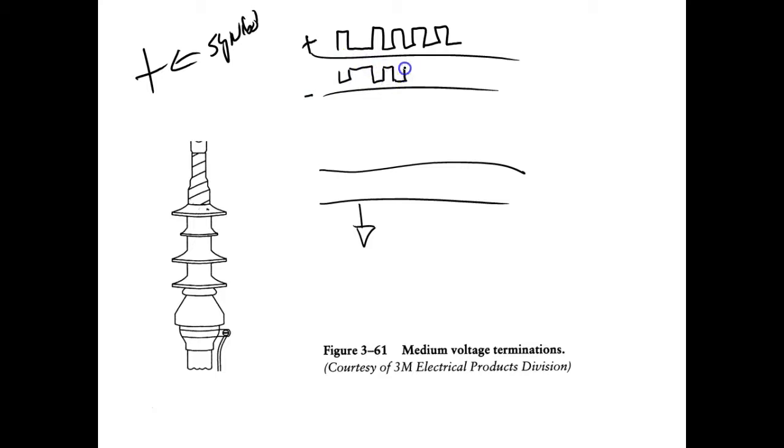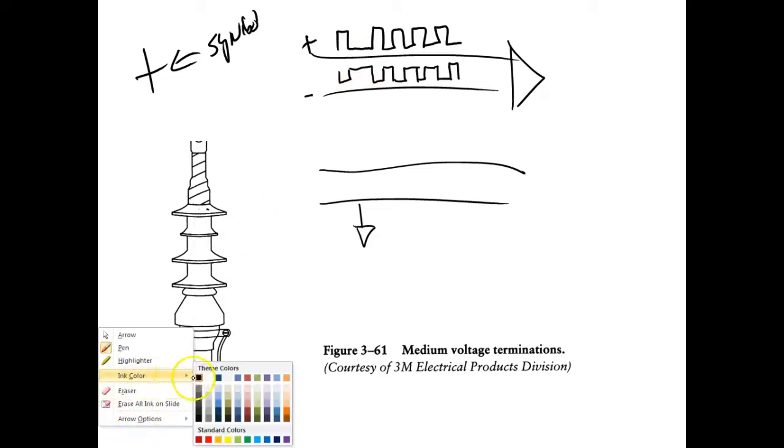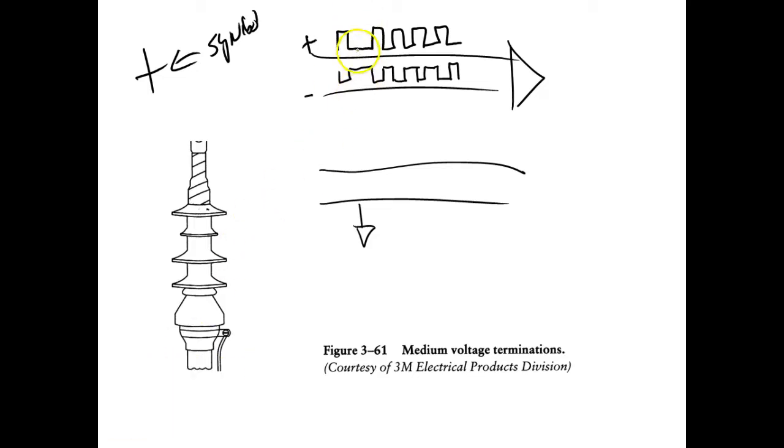If I can draw this good. So basically, it's a mirror image of that. And we came up with an amplifier called a differential amplifier, and these guys revolutionized communication. What a differential amplifier does is amplify the difference. A common mode signal, which would be if I had an electromagnetic pulse come through this thing, it would generate that. That's what we call a common mode signal. A differential amplifier would reject common mode signals. The only thing it lets pass is differential signal. This, guys, has revolutionized communication.